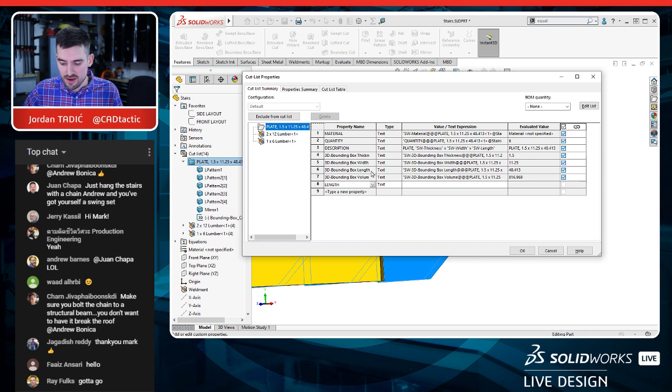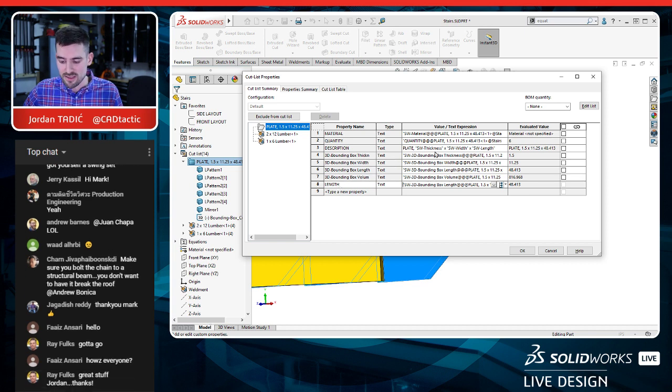And what is the length? It's going to be equal to whatever this length is. So if we uncheck this little automatic calculation thing there and hit Control A to select all that coding or that syntax that automatically calculates the length, I could just paste it right into that property. So now there's a length property that the table can reference.